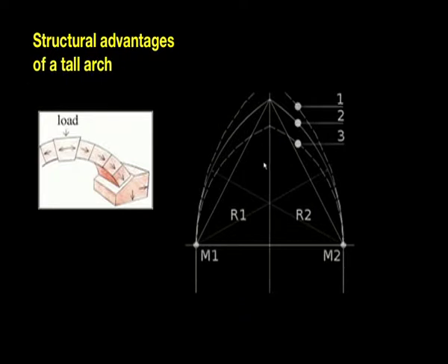If we could clearly map the structural components of these particular arches, we know that there is a vertical component of the arch which goes directly through M1 and M2, and there is also a horizontal component of these arches which goes away from M1 and M2 inside the piers or the columns where it is supported. These loads are lateral forces, which we know.